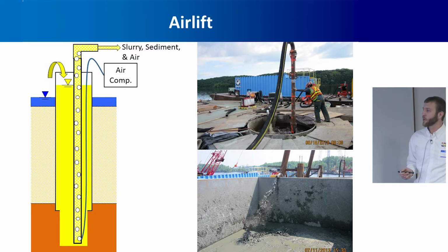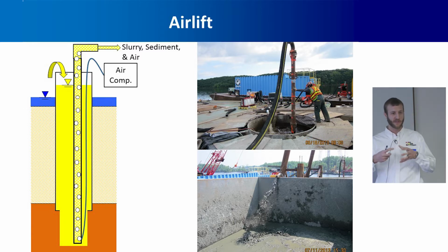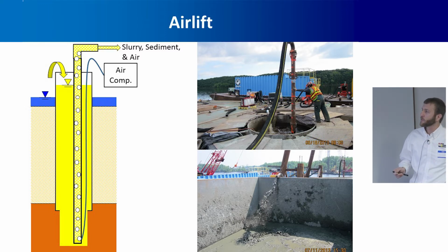So an airlift basically works by, it's just a pipe that we pump compressed air into, and those bubbles want to float up in that pipe, and those bubbles make the fluid in that pipe less dense, so the total density of the material in that pipe weighs a lot less. So just like sucking through a straw in a drink, the fluid around it wants to flow up that pipe. While we're doing that, we need to make sure that we maintain a positive head in our casing. Like I said, that's key at all times. It's easy to turn on an airlift and suck a hole down real fast.